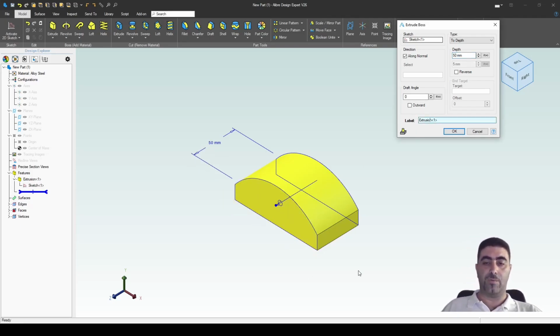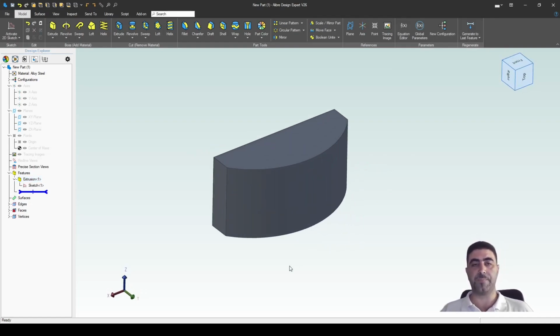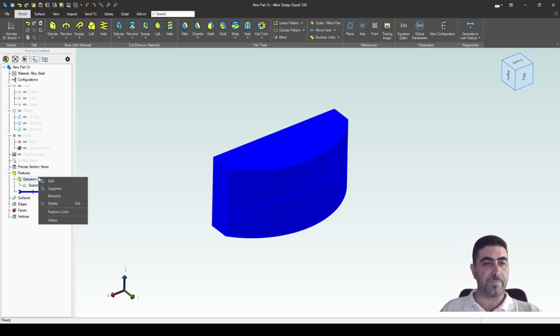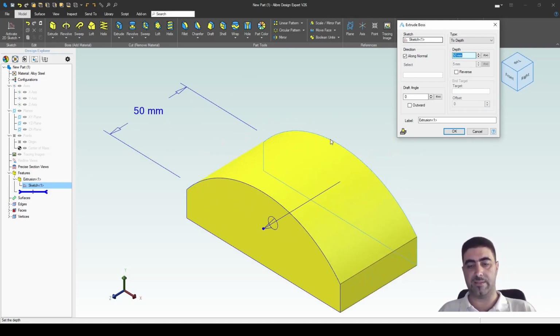So this yellow thing, right, is the sum of the points that, when projected along this normal, fall inside or on the boundary of our sketch, and also have a distance to that plane less or equal to 50 millimeters. Okay, so that is the geometric locus of points that create the solid through the extrude command. Okay, now the extrude command, so that is the core of it, right? That is the gist of it. That's what the extrude command does.